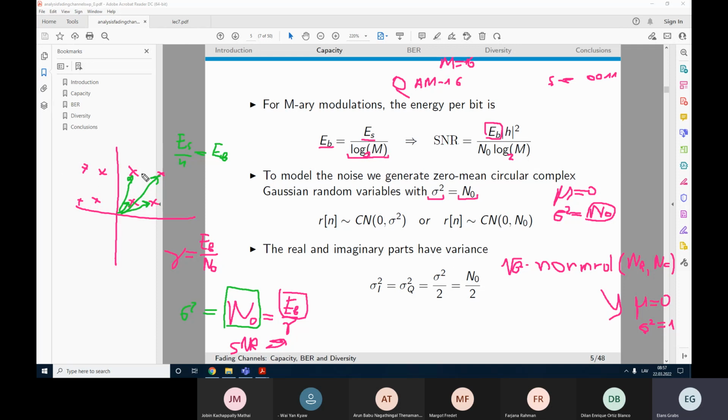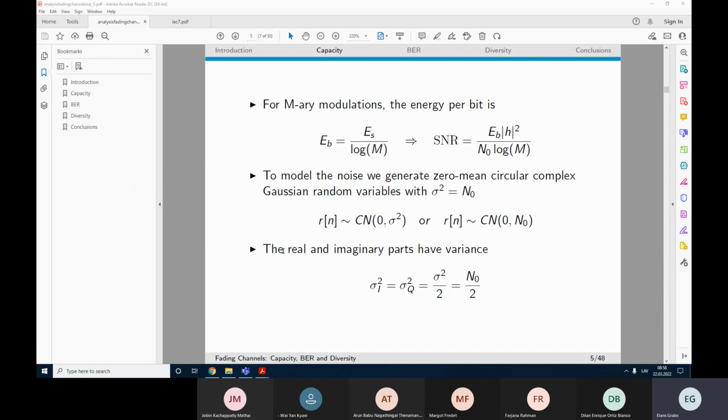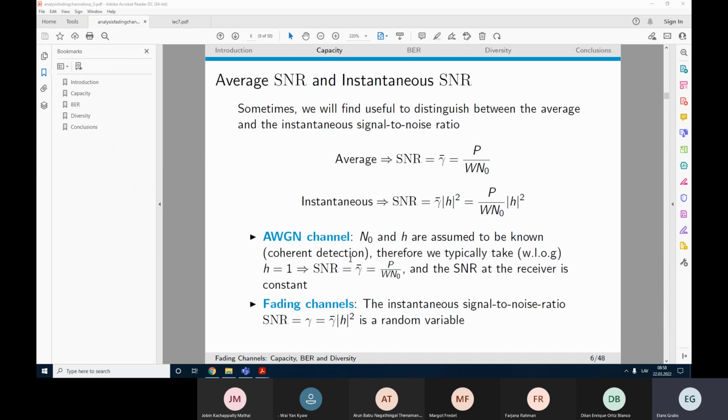We could have actually written our own AWGN function. It's not really that hard. However, here we need to remember that for the complex part, we need to distribute this noise power density into the real axis and the imaginary axis. So each axis will actually have half of the power density. Yes, the imaginary axis and real axis have only half of the total noise, so that both axes together have n0 complex noise. So that's one thing to consider. Let us go further.